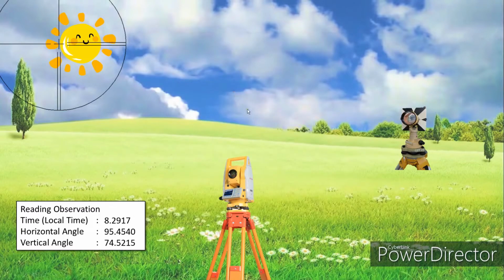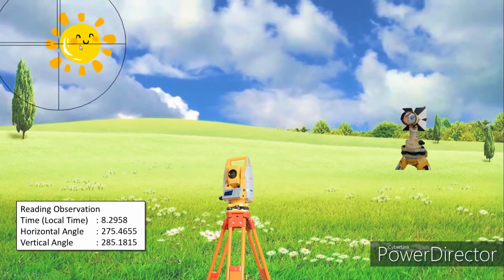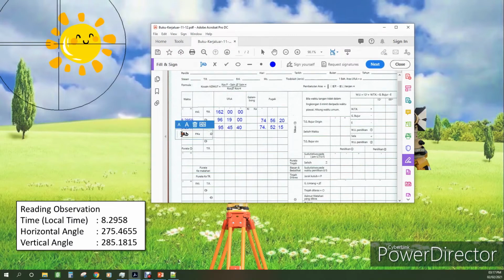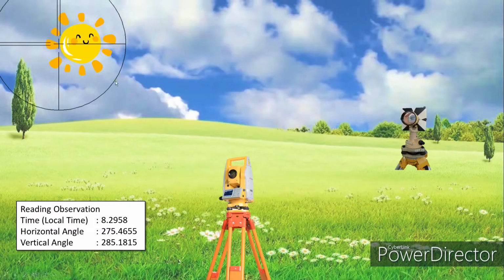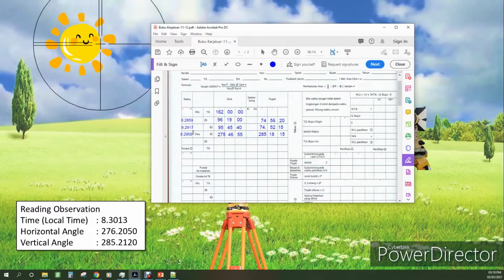Then we turn over our total station to circle right observation. We turn 180 degrees and make an observation on the left hand side of the sun, and jot down the data. Lastly, we move the target from the left hand side to the right hand side of the sun and also record it in our field book.